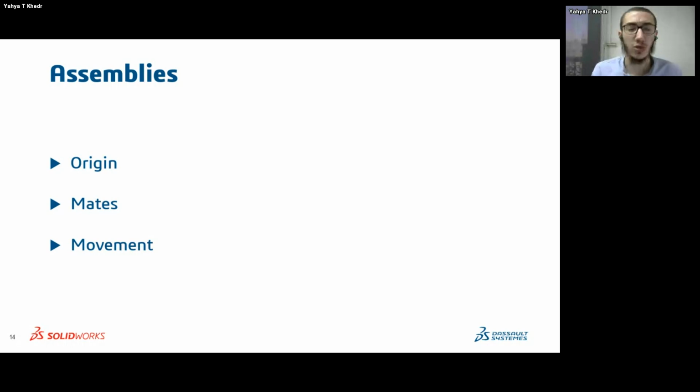So it's really important to identify where that assembly is in 3D space, because when it comes to a part, a single design, it's already going to be positioned around its own origin. The sketches will define where it is. But in an assembly space, I can put it pretty much wherever I would like it to be. I can drag a component and put it at the origin or far away from the origin, and then start assembling over there. So it's really important for me to specify where I would like that first component to be and build up based on that.